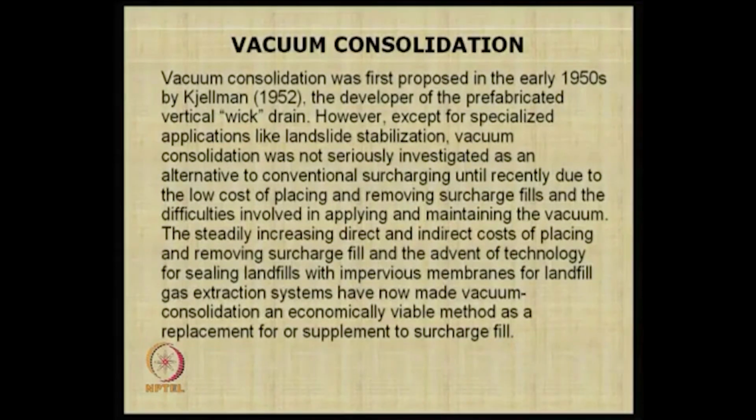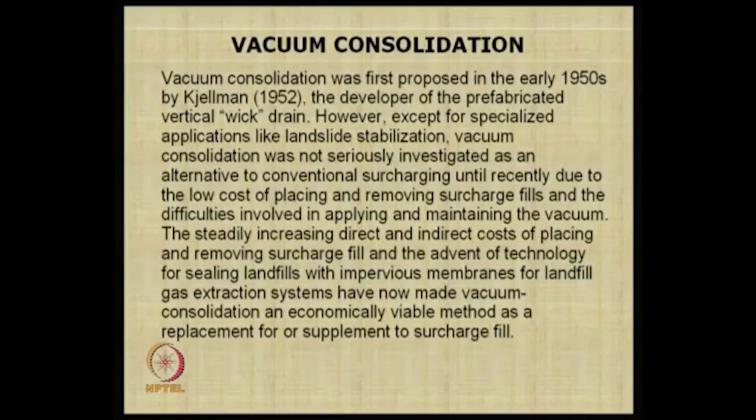Another important point I would like to indicate here is that there is another technique called vacuum consolidation. People proposed vacuum consolidation back in 1952. You create a vacuum, and the advantage is that you try to remove all the air present. Even in a saturated soil, if you just create a vacuum, there is a drainage that takes place, an accelerated drainage.